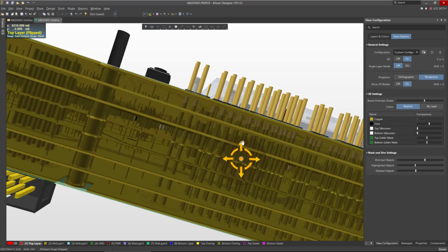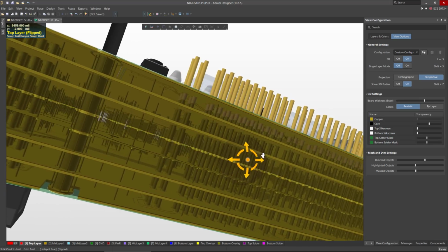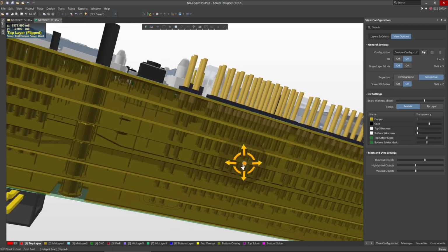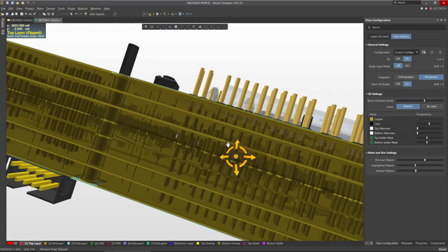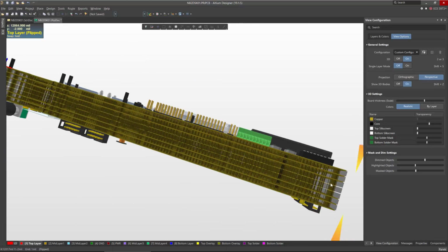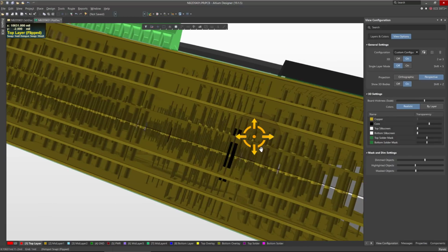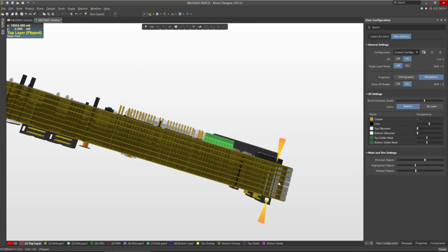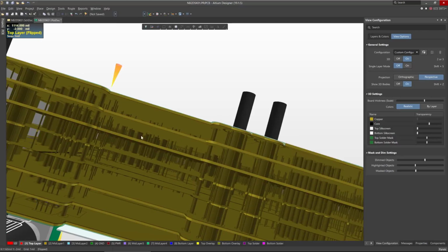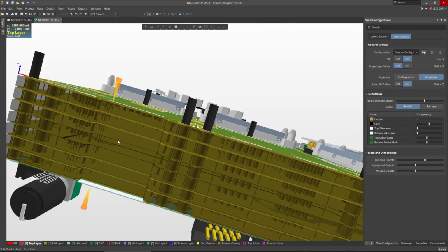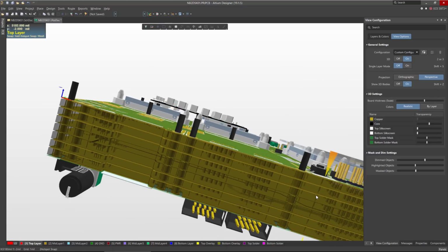And here you can see the vias connecting all the layers. And it's clear that they only have through-hole vias. I don't see any micro vias or buried vias or stacked vias or skip vias. So basically all of them are through-hole vias, and this makes sense. This makes sense because this is very cheap to be done. Once you go to buried vias and micro vias, the cost will increase significantly, and you really don't want to do that unless you have to do it.